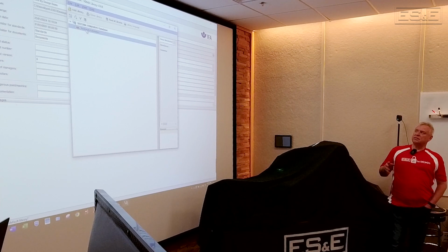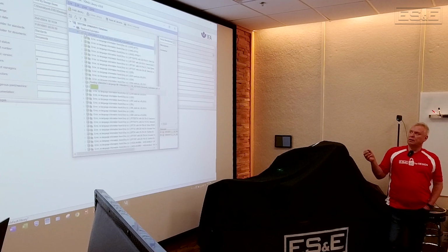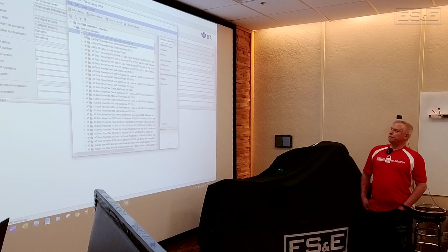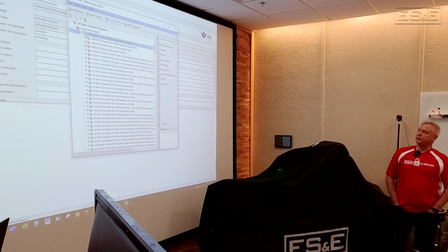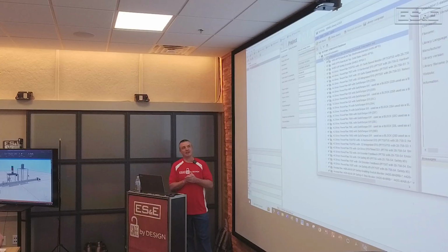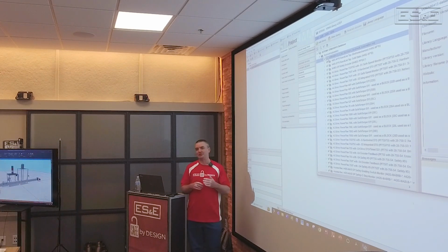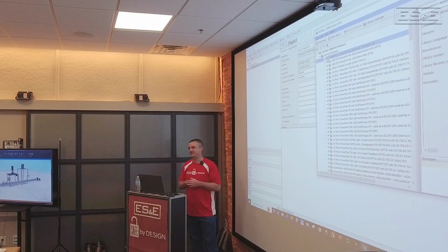So is this like an EDS file or something along those lines for each device? Do I have to upload it for each device, or no? Apparently I don't. Okay. So that one file is going to cover me for all the safety devices that Rockwell actually has. Okay. That's cool. Correct. So every safety device Rockwell's published, they have this documentation already uploaded into it. Again, that information that it's going to start calculating from, your diagnostic coverage, your mean time to dangerous failure, is all uploaded for those particular devices. So one file. Okay. That's the reason when we're doing the Safety Automation Builder, we're driving down and specifying the particular device that we're looking at.